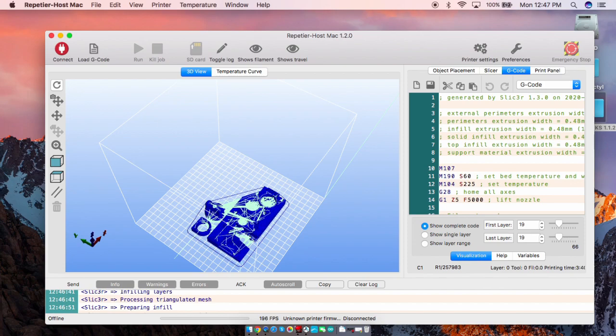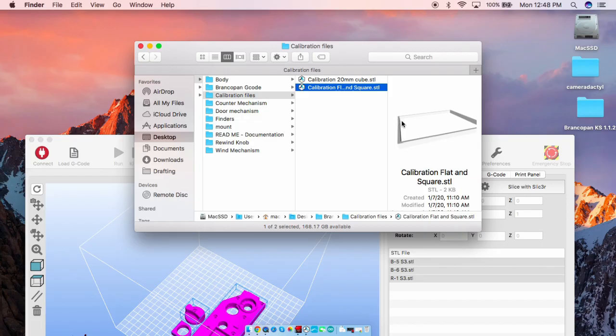Again, if you were going to print some in color, you might want to split those off into separate groups for printing in red or blue or yellow or whatever color you want to print them in. Now you can take all of these files, throw them on an SD card, and pop them in your printer and print. I like to print this calibration test first before I do anything else. It allows me to print lines along all of the edges of my print bed and just make sure that the nozzle is an even height above the print bed and nice and level as it moves around.